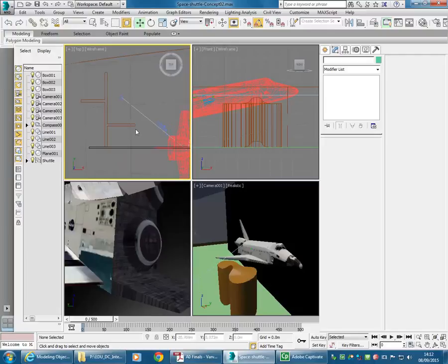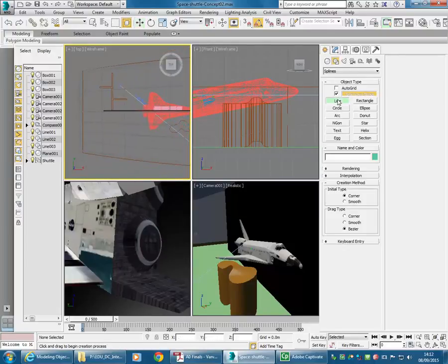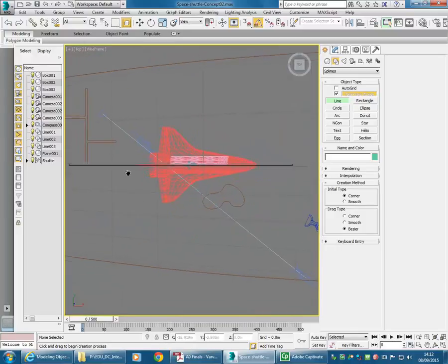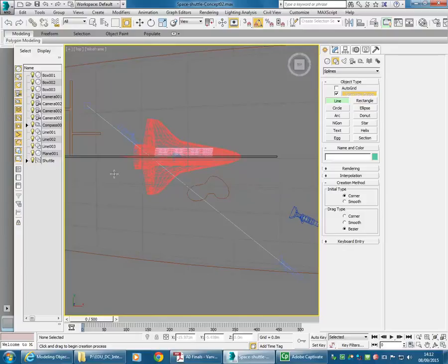So the final thing I want to show you is how you get those twisting shapes that often are more sculptural or based on ribbons or some idea like that. So again, using the line tool, I'll maximise this viewport, and I'm just going to draw, maybe coming out from the wall here, clicking and dragging to make it curve.